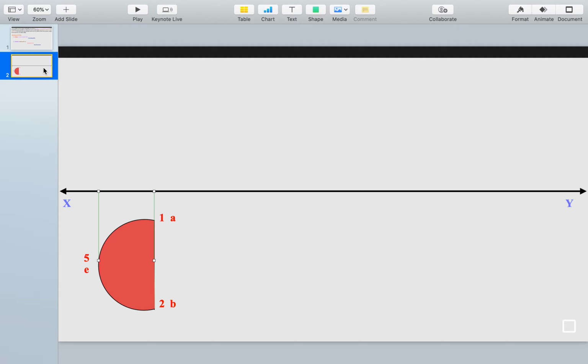Now we are required to draw the front view of the semi-cylinder. Before that, I have drawn here a center line of the circle, because the angle is given with the center line. The section line passes through a point 20 mm from any face on the axis. So this is the axis line I have drawn here. Now the front view of the semi-cylinder is represented by 1 dash, 2 dash, 5 dash, A dash, B dash, E dash. I have already explained the stages.